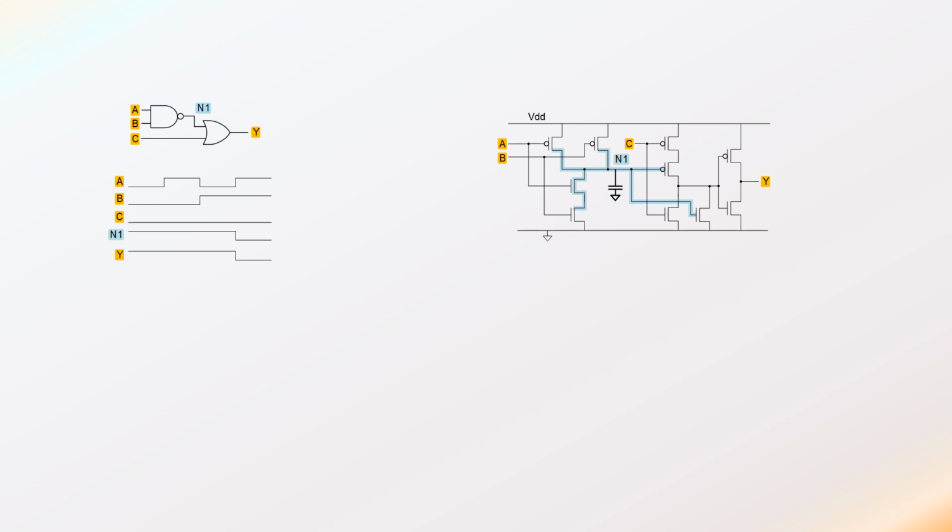In fact, you might have the idea that if I had other connections to node 1, let's say node 1 also drove another OR gate and another NAND gate and maybe an inverter, I'd add more and more conductive material to N1. If I drew the whole circuit diagram, you'd see more structures connected to N1, and that capacitor would get bigger and bigger and bigger. So the more things that are connected into a given node in a CMOS circuit, the larger the capacitance is.